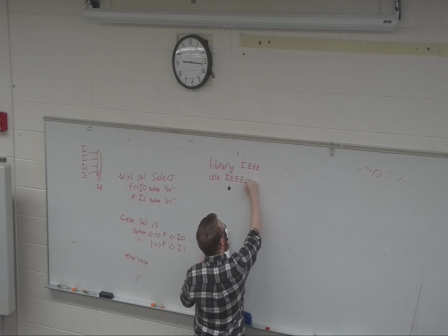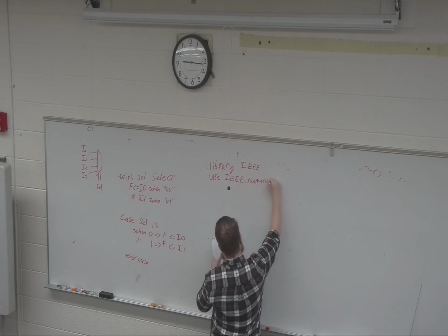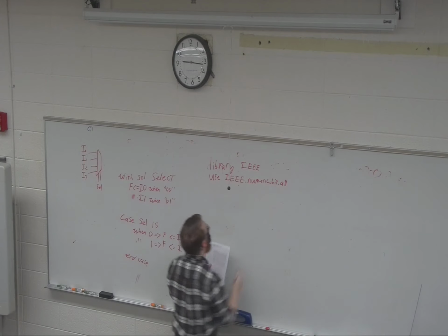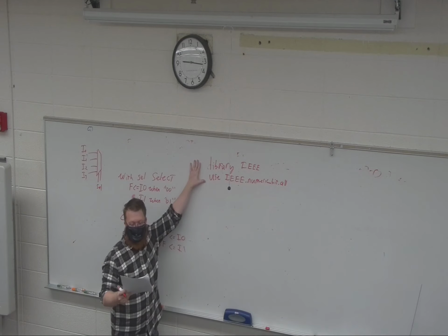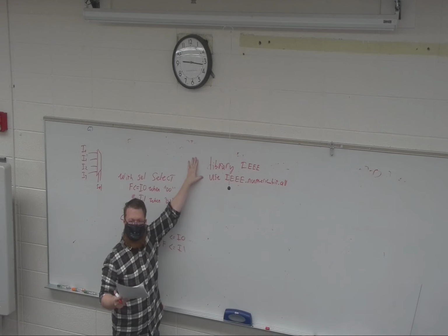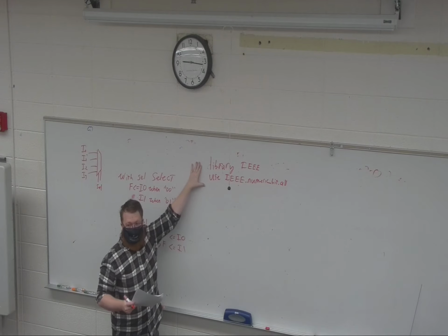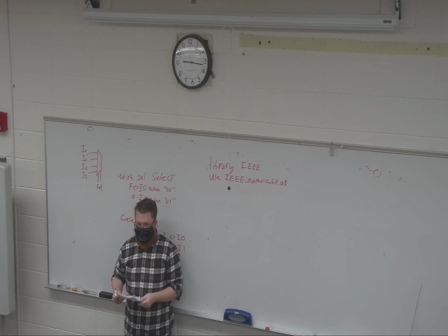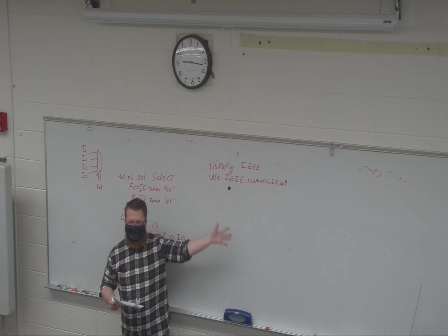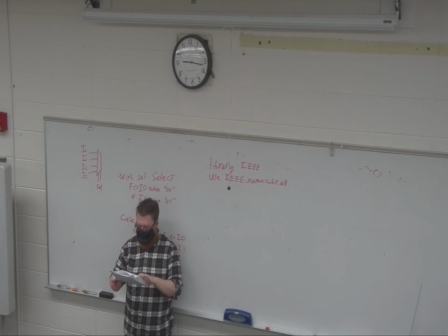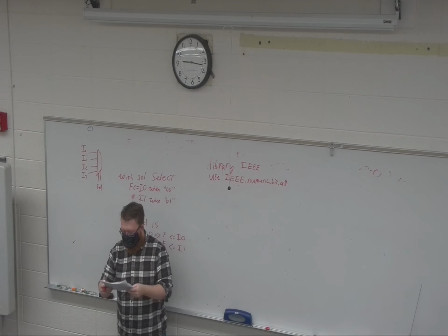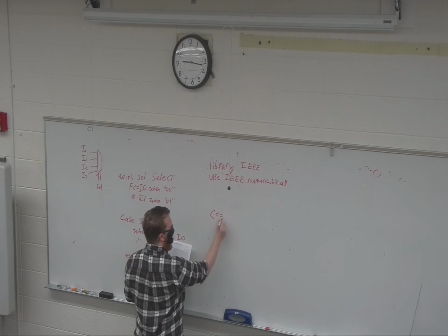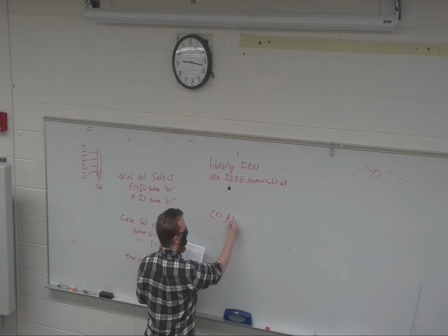Let's see. Numeric_Bit_all. That's an underscore. This lets us bring in the Numeric Bit Library from the IEEE main library. What this does, and is very useful for, is allow us to bring in unsigned and signed types. Those types can be as long as you need them to be, and they bring in overloaded operators, which means that your operators can do more than one thing, right?